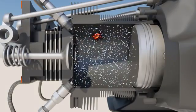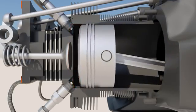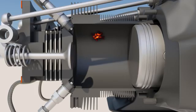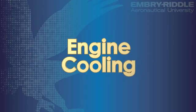Just as you'd expect, pre-ignition is simply when the fuel-air mixture is ignited prior to its normal time. This phenomenon usually occurs because of a lingering hot spot on the cylinder wall, usually caused by a carbon deposit that is hot enough to ignite the fuel-air mixture. Even when the engine isn't detonating or experiencing pre-ignition, the temperature of an engine can get quite hot. Like car engines, airplane engines have a cooling system in order to prevent engine damage or engine failure.